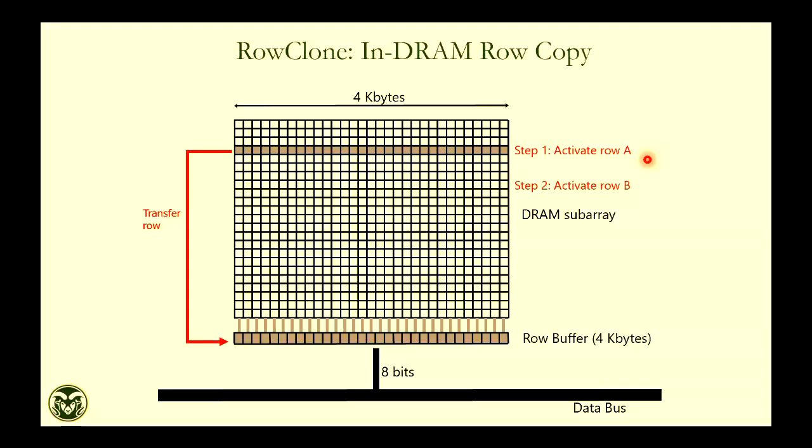So now it is not a read operation. The second activation is not a read operation, it is a write operation. Is there a possibility of adding data? No, because it is digital, zeros and ones. So no matter what the state of row B is, whatever data is in the row buffer will be written to row B. The first step is the read operation; after it, row A is written back, so row A is done.